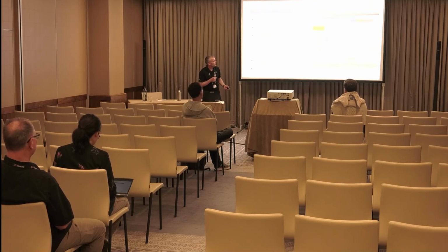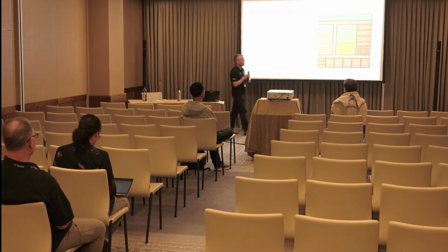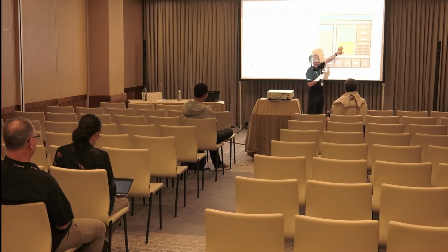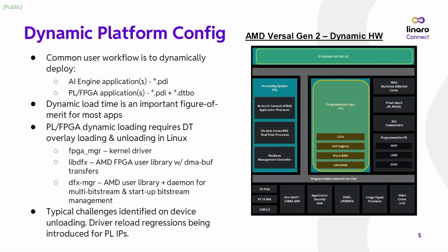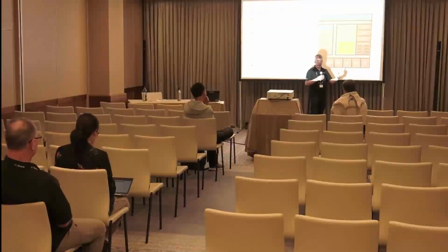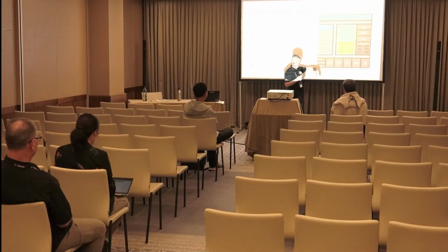Yeah, so what will happen is, this FPGA, we have what we call CFI, a configuration interface into it. If I have image A, which is my park mode, and image B, that's a firmware blob in the view of Linux. From user space, and ultimately we would want to run this all through Secure World in the future, but today, Linux will make a call down into FPGA Manager via our user space library.